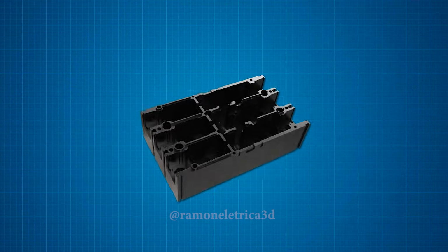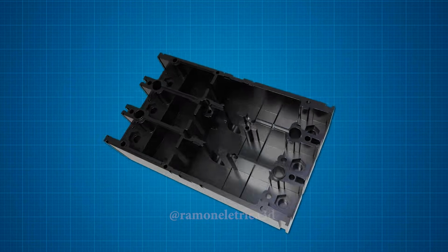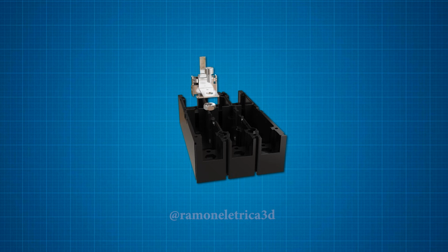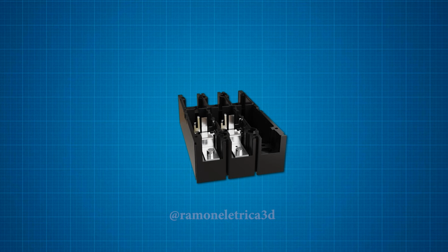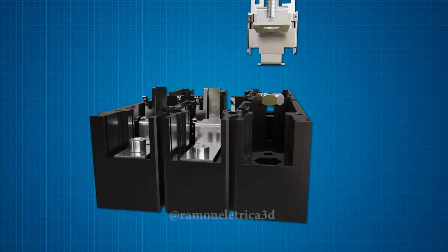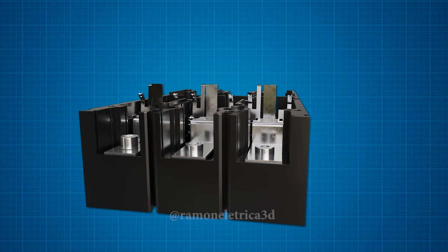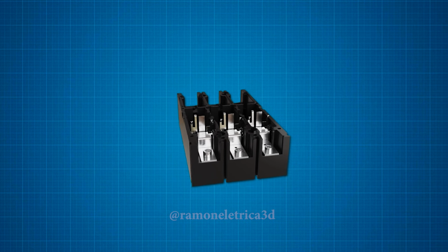Now let's understand how the MCCB, molded case circuit breaker, works. We'll start with the MCCB terminals, which are the points where the cables are connected. These terminals are made of metal plates, and the cables are connected using a ring-type terminal, lug. The nut located at the bottom of the plate is used to secure the screw that tightens the terminal. This metal plate is where the cables leave toward the circuits.